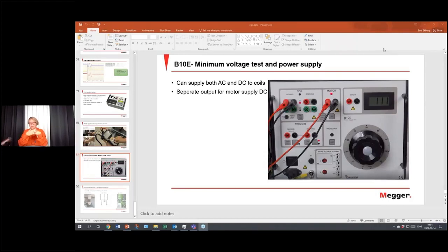In general, when there is a real fault on the circuit breaker, this value tends to rise quite high. So if you expected 25 and you get 50, that could actually be a breaker in perfectly good condition. But if you get hundreds of micro-ohms, that's a totally different story, because if it gets high enough, it's more or less a heater, because you have such a high current flowing through it. Normally I would say it should be under 100 micro-ohms on a normal circuit breaker. But if it's an old one, those figures can really vary. And that's what can be faulty.